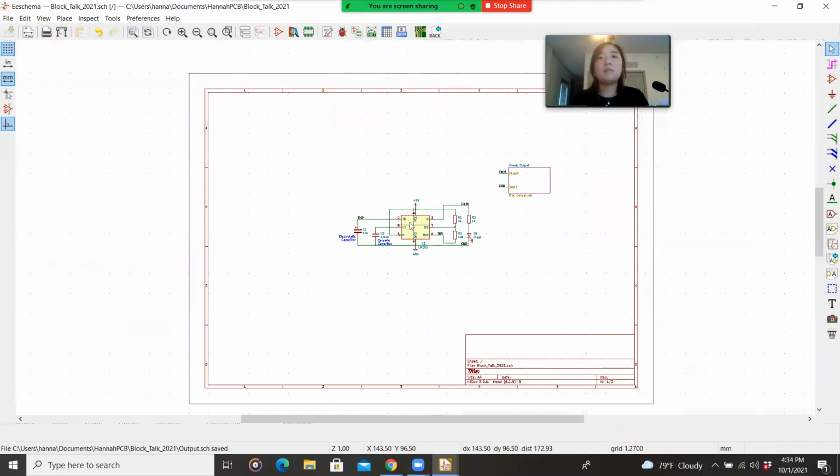An interesting thing with the SOIC and all those things is that a lot of ICs tend to be one of those common shapes. So a lot of times you can find the footprint in KiCAD rather than having to make your own. Okay, so now the last step before we move on is we can perform an electrical rules check.